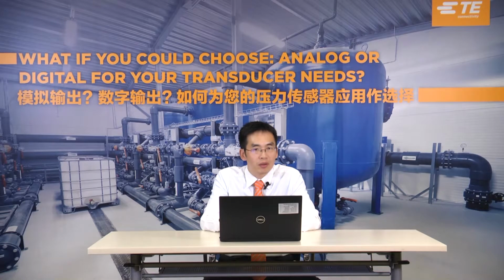The basic sensing element has no change. It is our mature technology, microfuse. The Wheatstone bridge detects the pressure change and then converts that change into an electrical signal. And then the output has no change. It's either analog, a linear voltage or current output, or digital, I2C output data format, with a digital signal which contains pressure and temperature data at the same time.